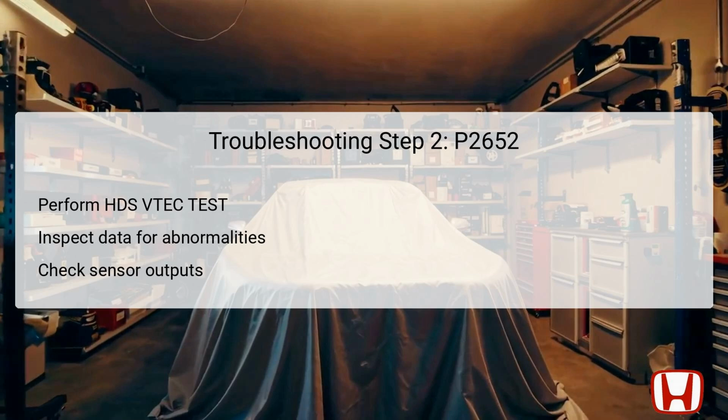This test serves to confirm the operational status of the VTEC system and helps in diagnosing if the persistent high signal from the rocker arm oil pressure sensor is indeed the root cause.